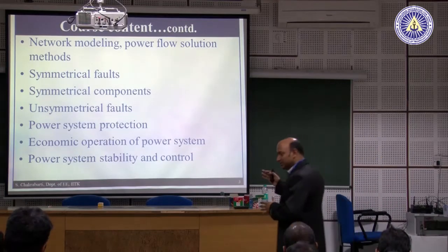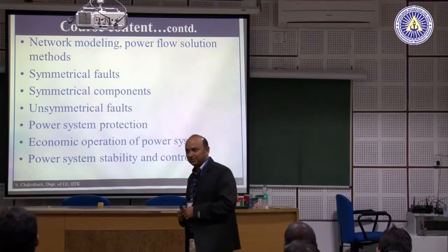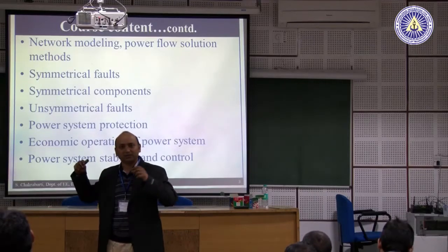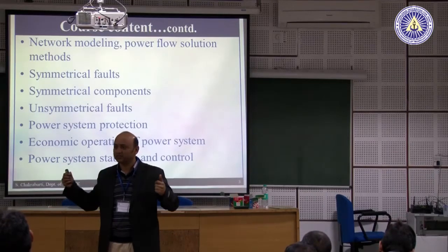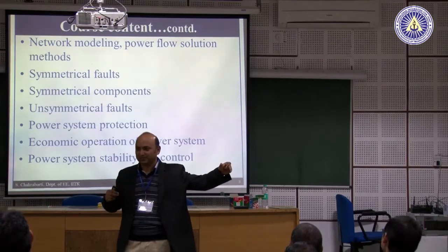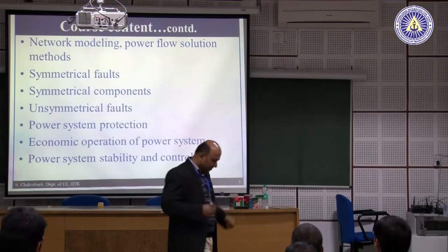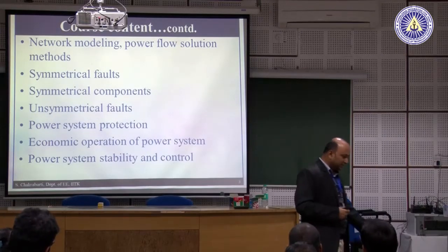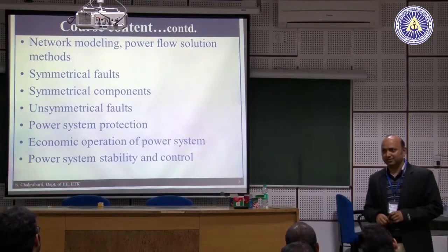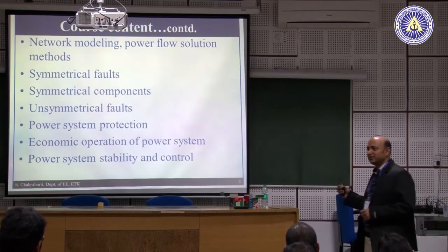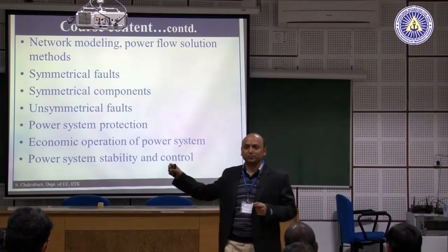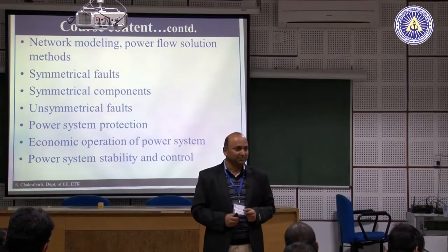So, how do we do this? We have something called economic load dispatch, which tells you what is the optimal value of P, and then from the control center there is an automatic load frequency control mechanism through which we set the value of P. And what about V? The main reason is that the generators are usually equipped with automatic voltage regulators. So, the terminal voltages are usually controlled. Thereby we can control or set the value of P and V, right.